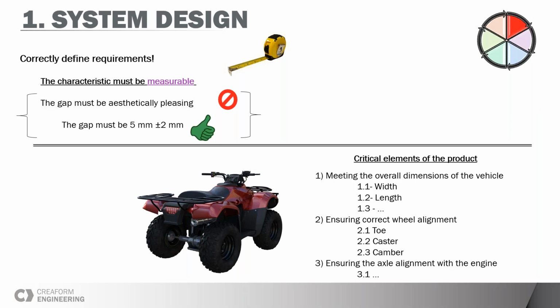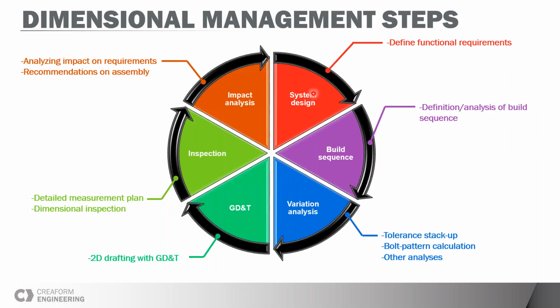But also with 3DCS, the software, sometimes you have critical components that are more impactful on the rest of the assembly. When you have that, maybe you can estimate some of the portion, and then have real physical measures and statistical studies to input into 3DCS and see what's the impact on your whole assembly. So before doing the whole truck assembly, you might say, oh, this part is really sensitive, it will have a lot of impact, so the whole assembly is really sensitive relative to this specific component. So we're going to see, if I have variation on this one, what it gives on the rest of the assembly. That's what the software is used for.